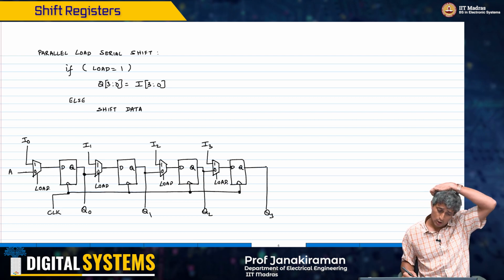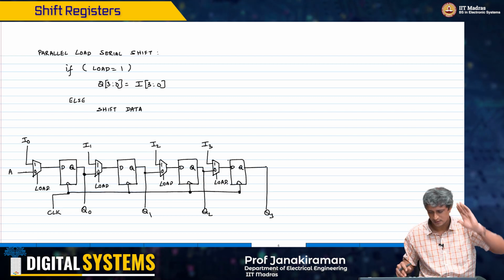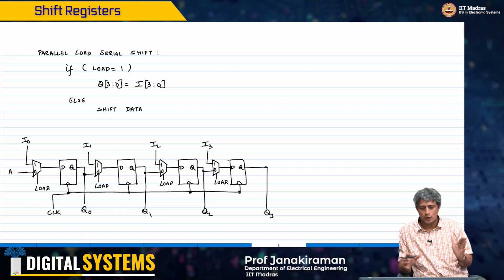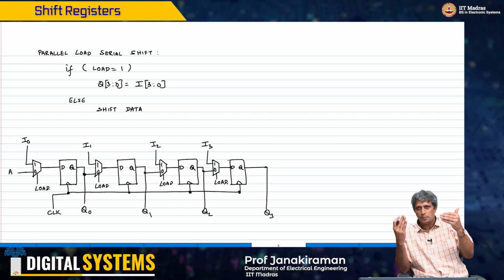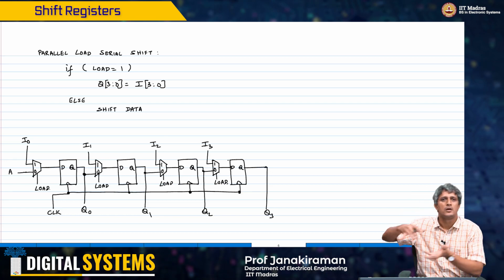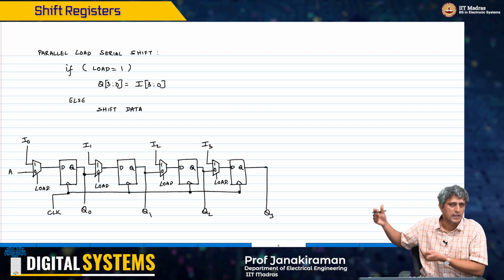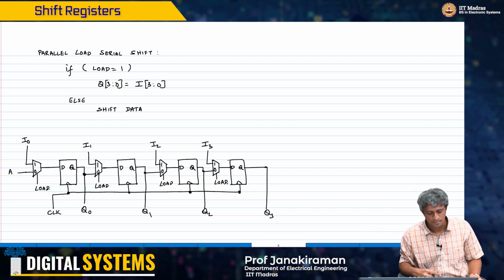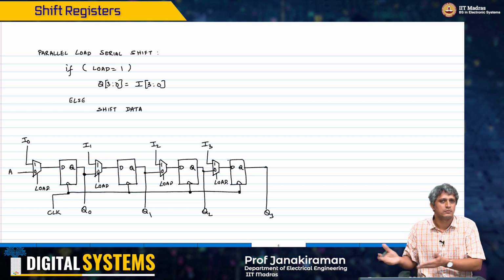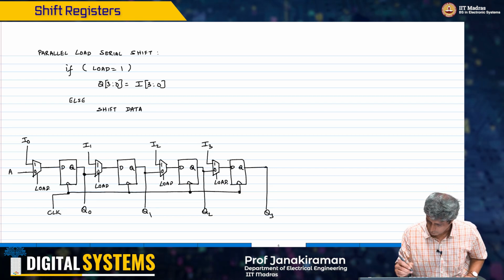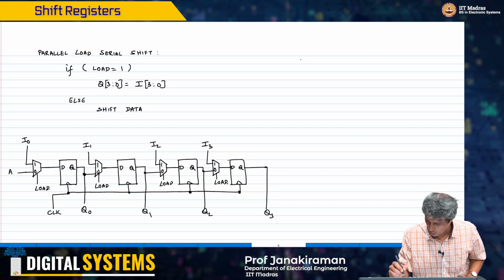Okay, so now with respect to this, what is happening is when the load is equal to 1 on all 4 flops, the multiplexer's arm where the input can be fed in gets activated, and therefore those 4 inputs will be made available at the output when the clock pulses, right? When the clock samples the data, and then you can do some serial operations and the data will actually move, right? So again, it's important to be able to draw these timing diagrams appropriately here.